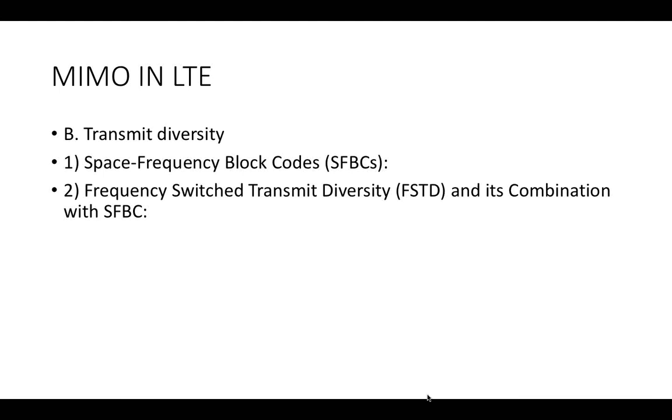This family of codes is designed so that the transmitted diversity streams are orthogonal and achieve the optimal SNR, the signal-to-noise ratio, with a linear receiver. Such orthogonal codes only exist for two transmit antennas.